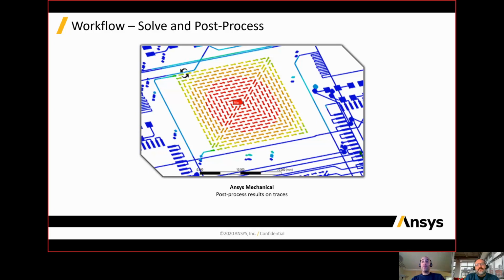I mean, the picture that you get at the end, you can actually see the efficacy of the individual vias and how good they are, because you can change plating thickness. You can actually work with it in a way that is kind of hard to do if you're just doing regular trace mapping, and kind of expensive computationally to do if you're trying to do a full 3D trace model. So that's a really good one.